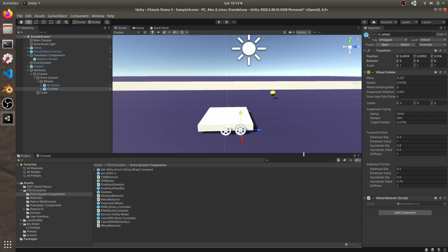So you couldn't see it, but what we want to do is put it up toward the front of our bot. Now, the bot's, again, 16 inches to the very front edge here, so we need it back a little bit. So let's say we'll set Z to about 14 inches, right? So in meters, that's 0.3556. And there we go. It's right in the front of the robot.